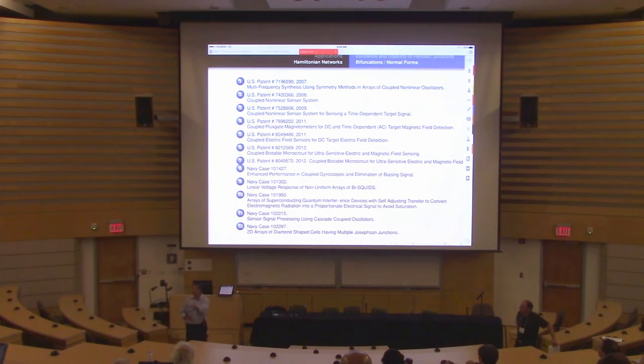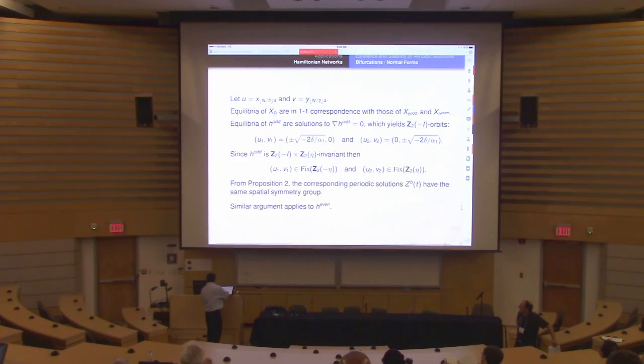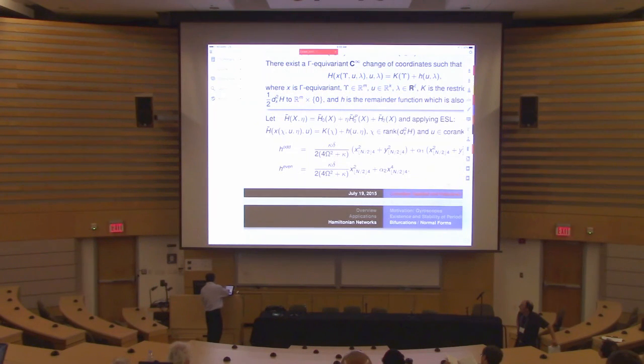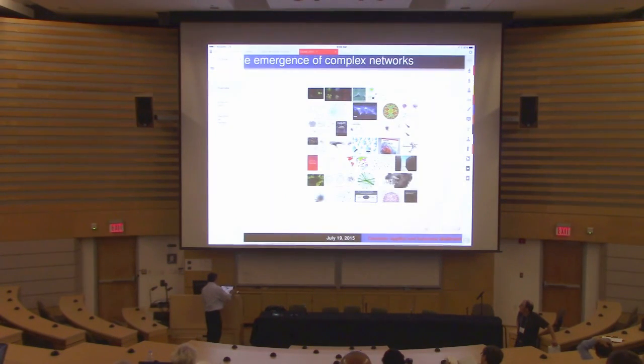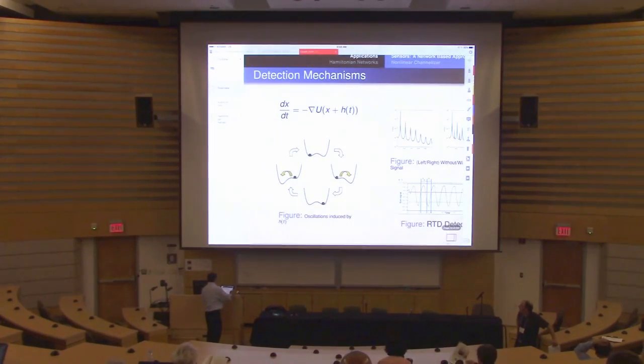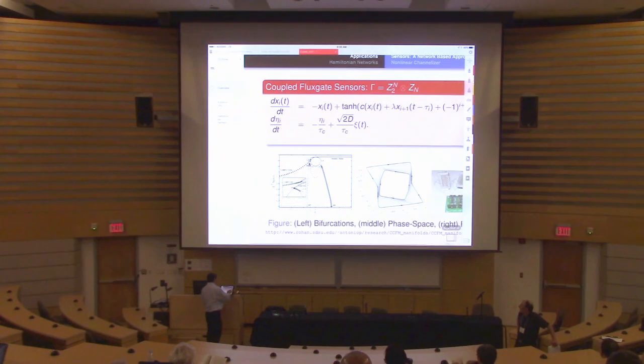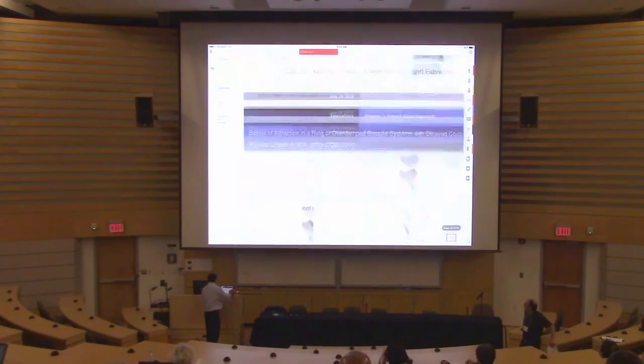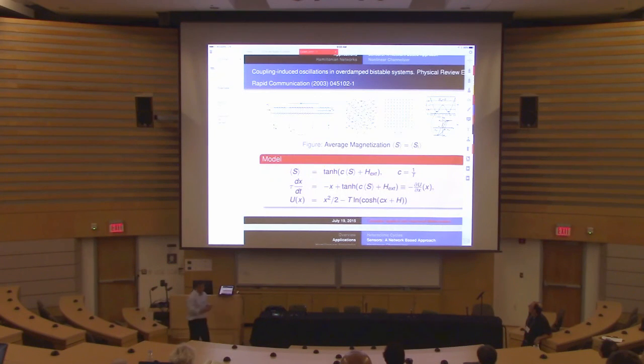But to answer your question, what Myra found out is that you have about plus or minus 10% variation in the non-homogeneities of the individual nodes. So the variations, by the way, where do they come from? In the case of the flux gate magnetometers, just imperfections of the ferromagnetic materials.